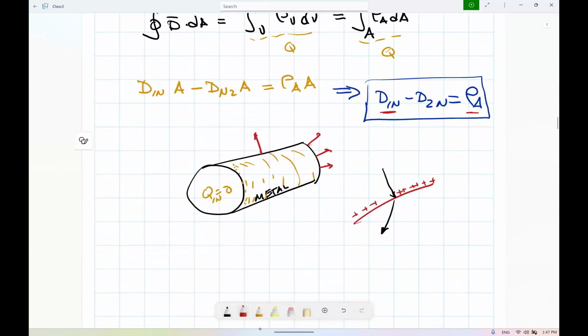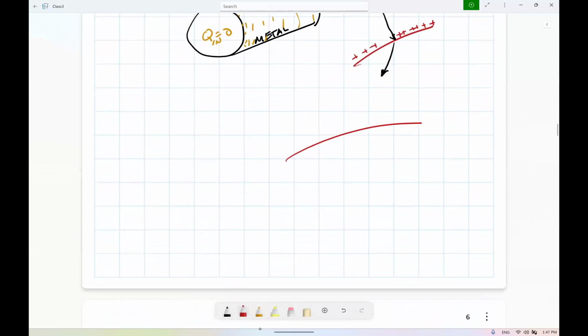If we do a finite elements thing, so I have that, and you are meshing, right? You are meshing, and let's put triangles. Triangle is the most versatile shape that you can have. So you have that. On the other side, the mesh will have to be similar to that, right? Maybe inverse, but the points, the nodes need to be the same. Otherwise, you're creating a problem.